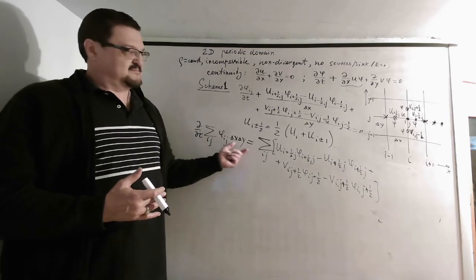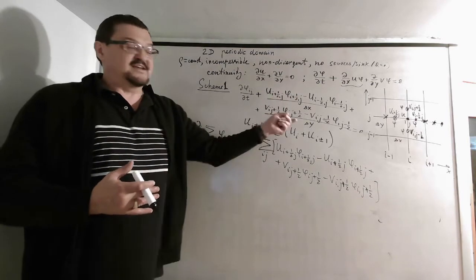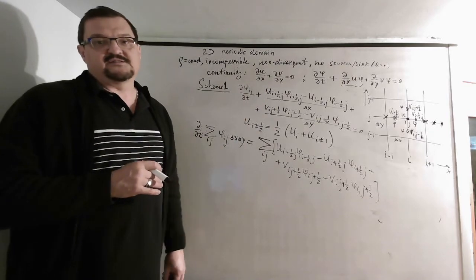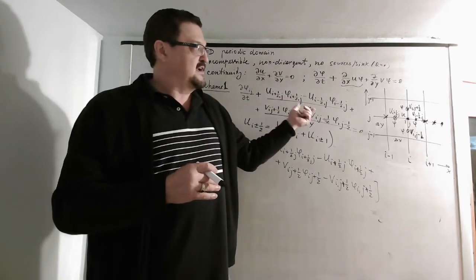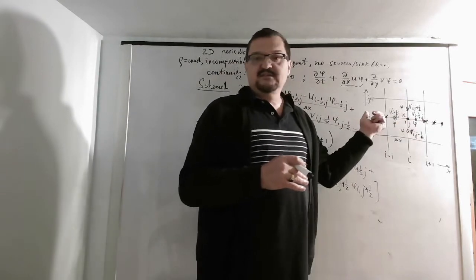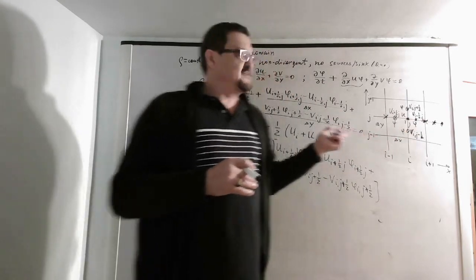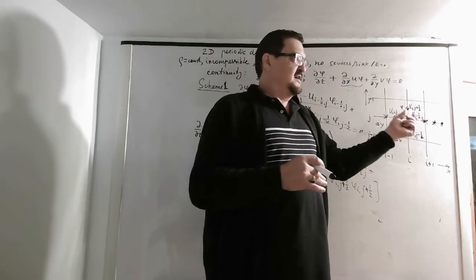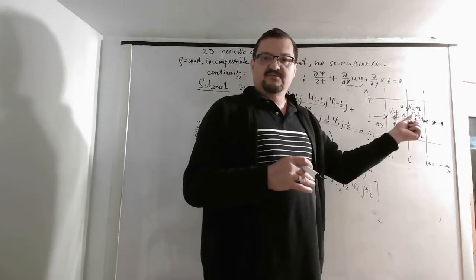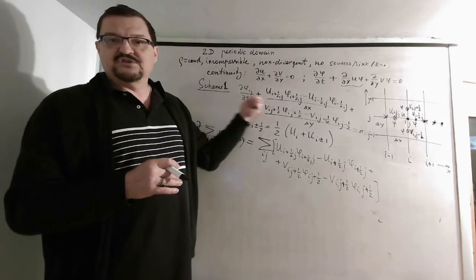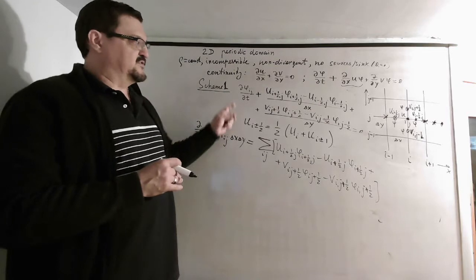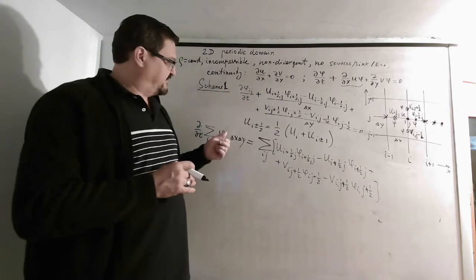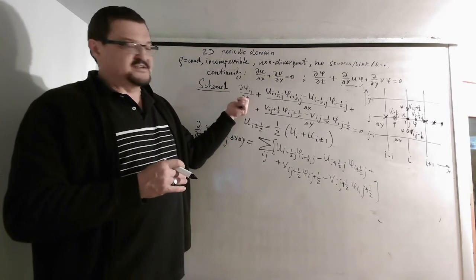Basically automatic. So as long as you wrote it like that, one flux minus another flux, regardless of how you represent this flux, you can represent it in this case by averages, or previously we didn't even average anything. It's still, as long as you do it in the flux form consistently, and you use the same flux on the left boundary as on the right boundary and so on, your summation will cancel all those fluxes out. So that's why flux form always basically assures conservation of the quantity itself that is predicted.